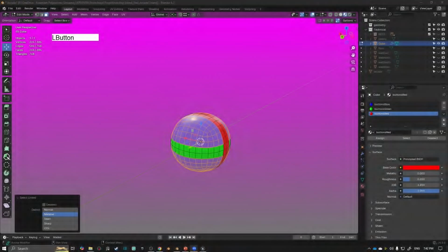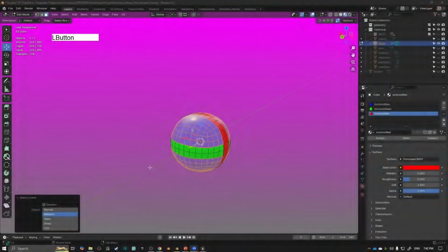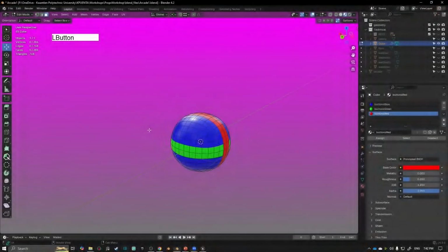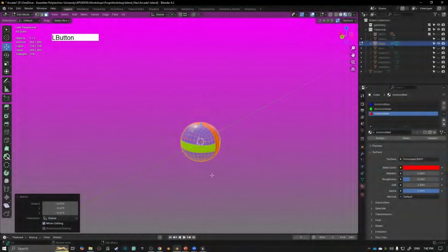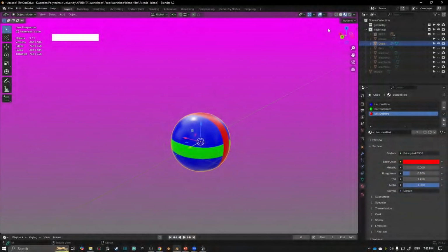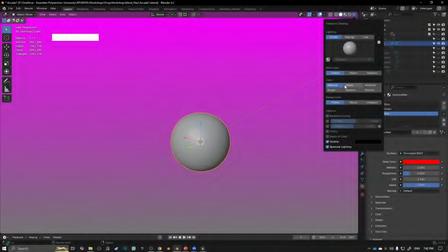Yeah, the mesh is going to look weird in Unreal for sure. That looks like the wrong materials applied to it. And this one right here, I can show you how to fix this. Somewhere along the line something got scaled in negative, so the normals are flipped. For example, if I take this object and I scale it all the way down, and now it's scaled to -1, 1, 1, it looks fine right now. But I'm going to click on this little arrow and go backface culling.